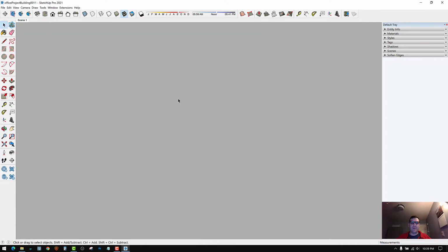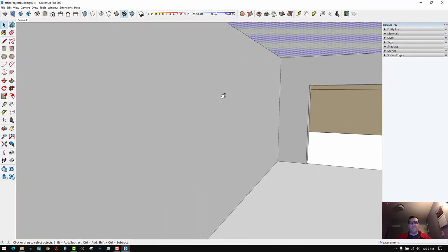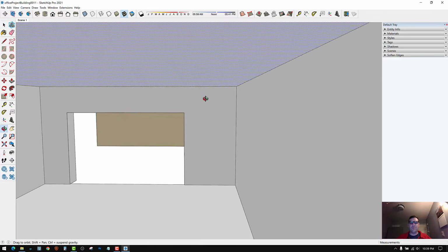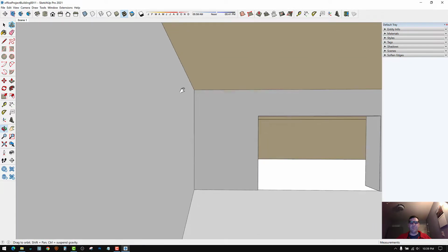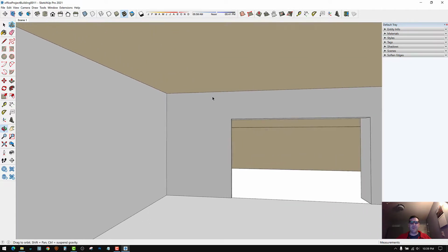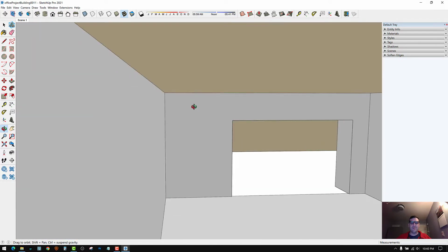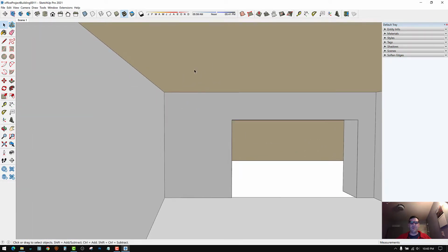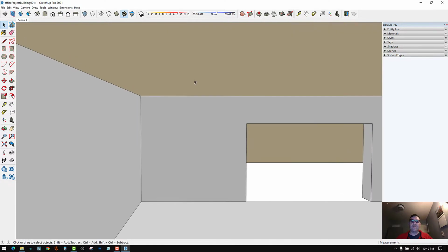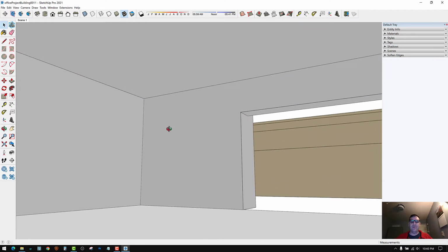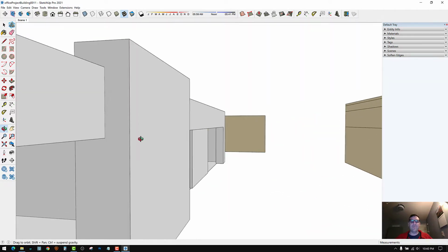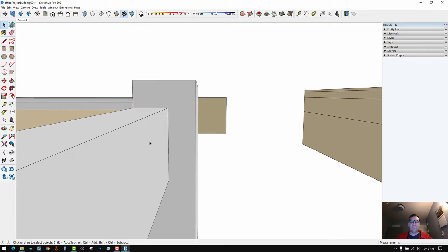When you're rendering in a render engine, some render engines will do double-sided materials and some won't, especially video game based GPU rendering engines. They like to do just one-sided since it saves on computer resources. So when you're modeling, you always want to model so that the visible face is the exterior face.